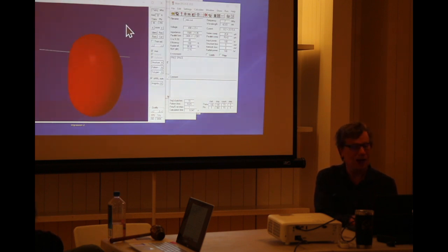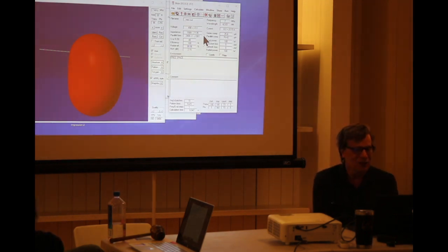Here we have our classic dipole design, okay? No problem with that. But our impedance here is a little bit unwieldy, okay? 1,588 ohms minus J 1,135, okay? So we have an issue here. Now, see how minus that J is.